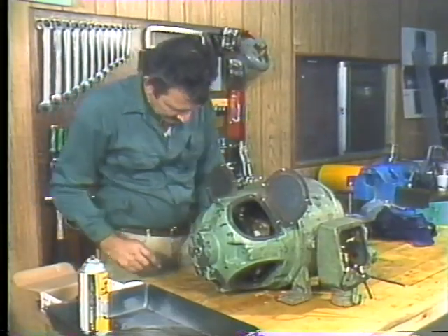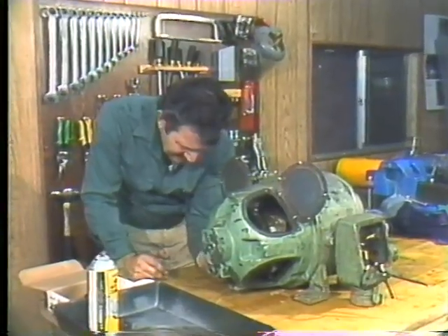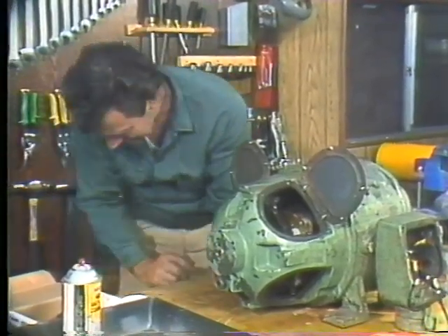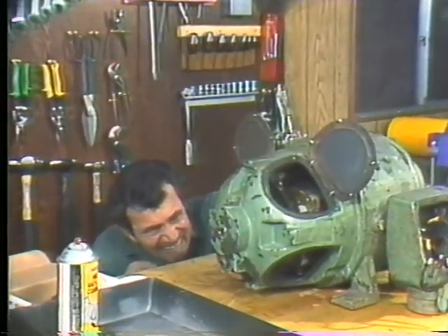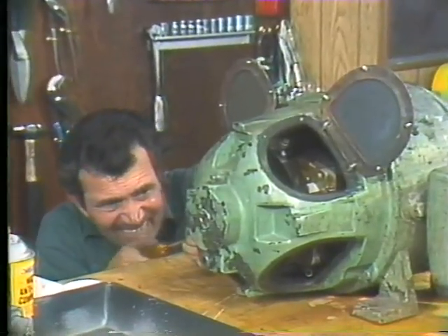Now, if this all looks good, you may have a bad bearing. If this is the reason for the motor not turning freely, it will have to be taken apart again and the bad bearing replaced. Never start any electric motor unless the shaft is free to spin when turned by hand.